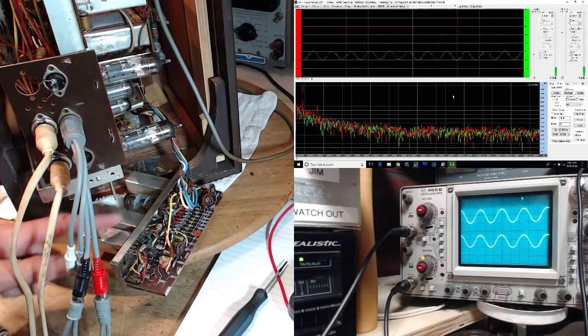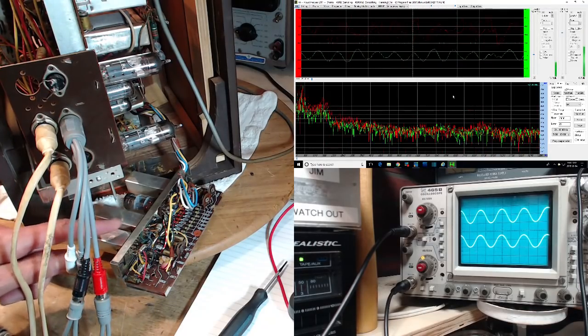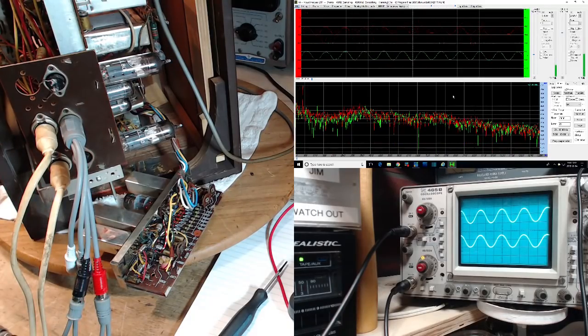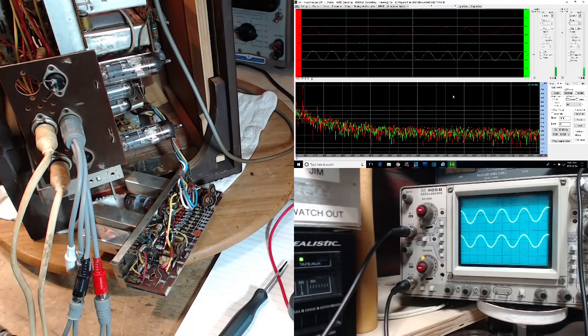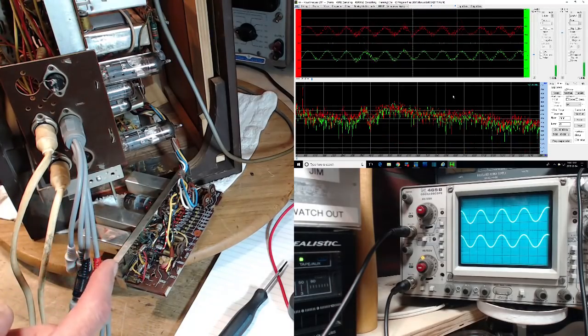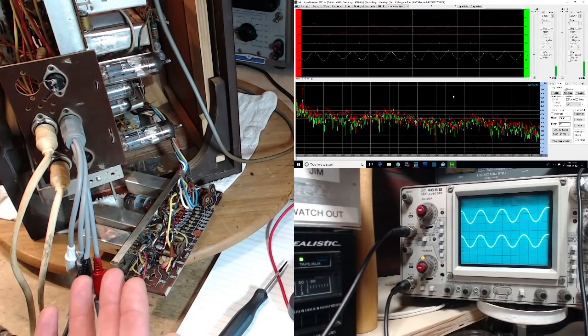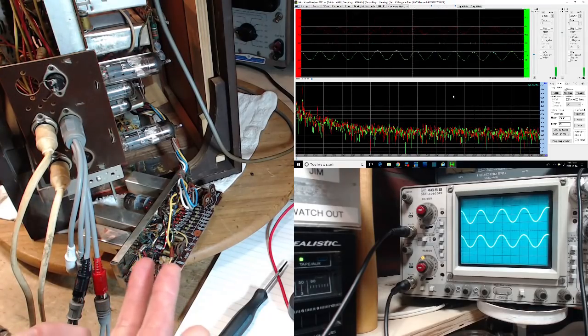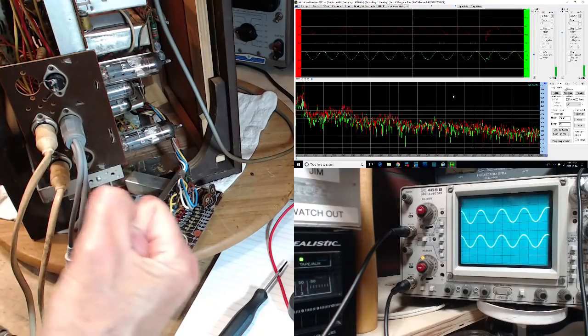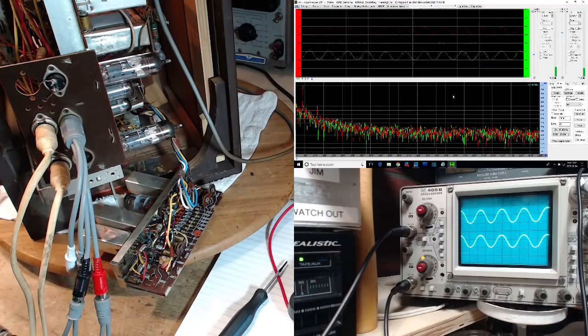We have quite a few coils and transformers up here, and something over here, all of which are open for adjustment. To what end? So part of what's going on down here is it's taking the 19 kilohertz and doubling it to 38, and then boosting that in a resonant circuit to give it a little bit of oomph. Almost certainly the tube is involved in this.